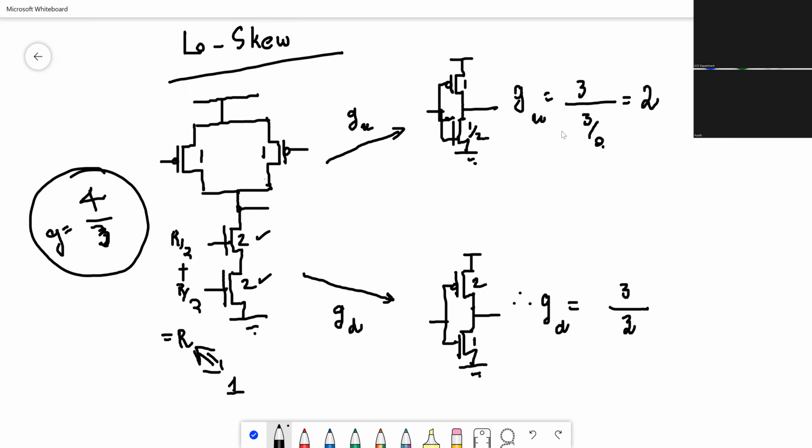So how can we improve the gate? It could be that in some gates, for example, the 1 to 0 transition might happen many times, but the 0 to 1 transition may not happen so many times. In those particular cases, we can use this skewed gate. 1 to 0 will happen very quickly, making the gate very fast, but 0 to 1 does not happen so often. So whenever it happens, it will take a little extra time. But because it's a rare event, we can ignore that particular occurrence. So this is the idea behind skewed gates.